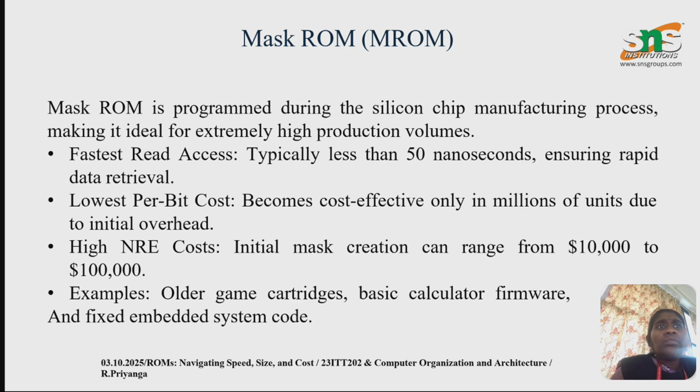Why is it called MOS-ROM? During chip manufacturing, a special template called a photolithographic mask is created. The mask defines which bits will be ones or zeros inside the ROM. Once the mask is created, the chip is produced exactly with those data values, hence the name MOS-ROM.